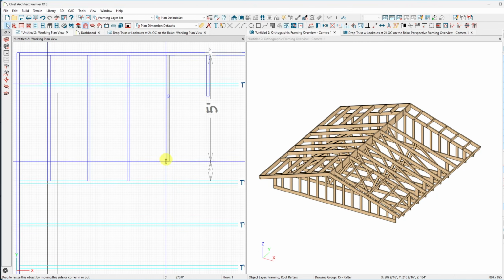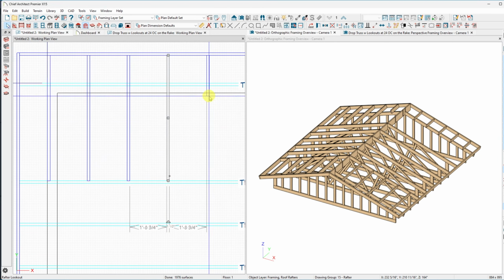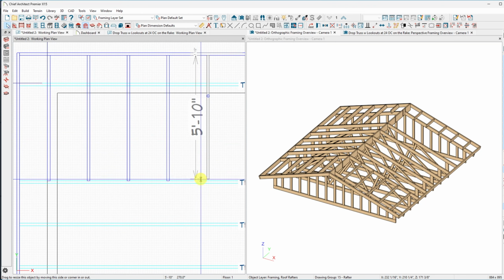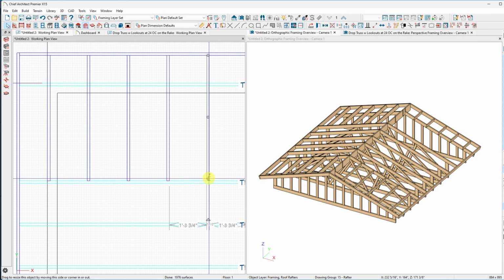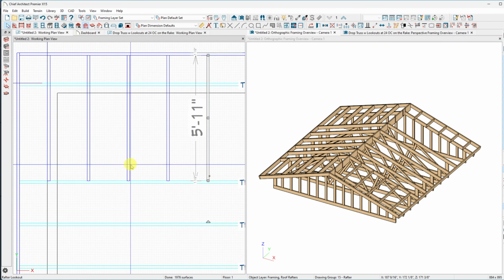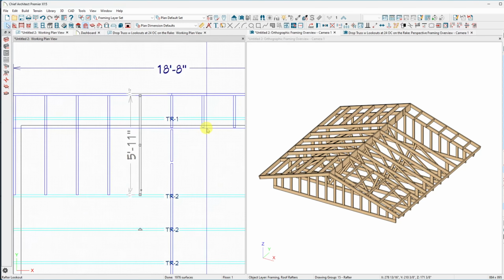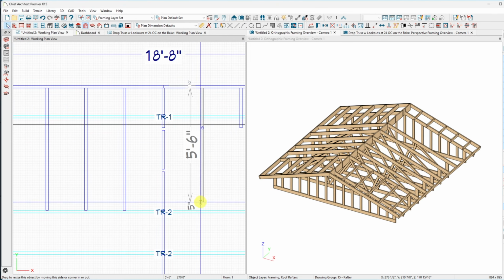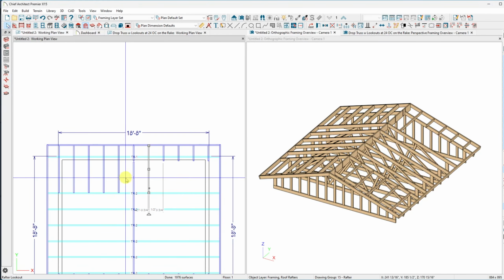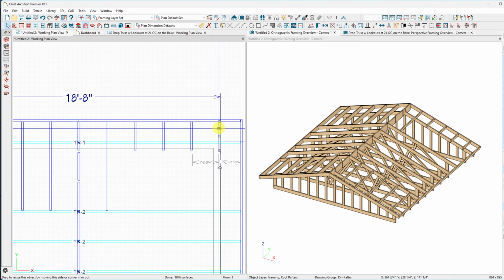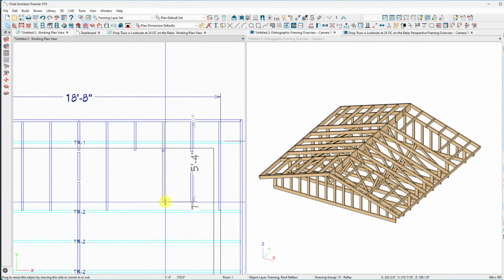Now the one thing also that Chief, they haven't figured out is the selection tool. Man, it's nice in AutoCAD to get that window selection. And all you have to do to get a crossing selection is go from right to left for crossing, left to right for window. And what a great feature. Here, I have to hit one of those special buttons and then hit another button.